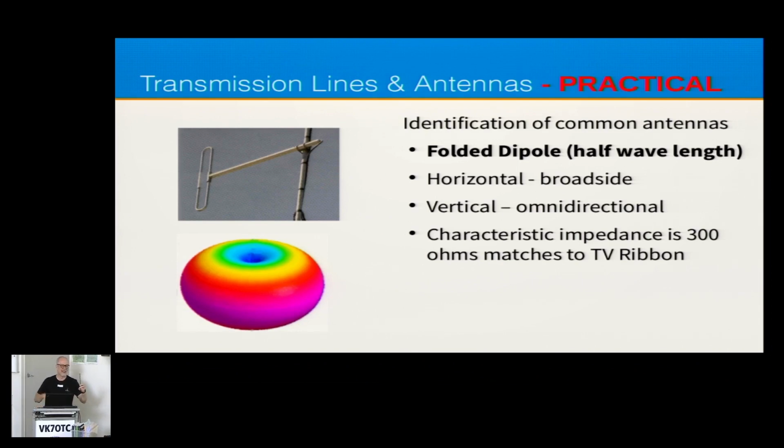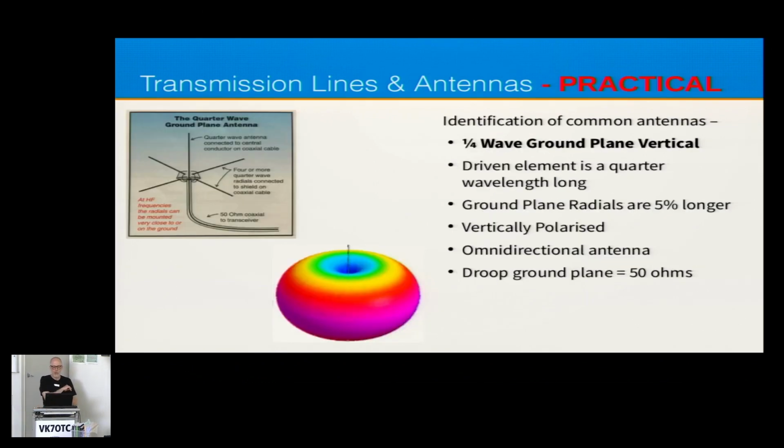And I talked about television antennas using 300 ohm line. If you get a coat hanger and you bend it round and you connect it to a bit of 300 ohm line, that's actually pretty close to where the television signals are, and it's a great little folded dipole antenna. Really quick, really dirty, works really well. People don't do that anymore, but they used to. That's what we use 300 ohm line for.